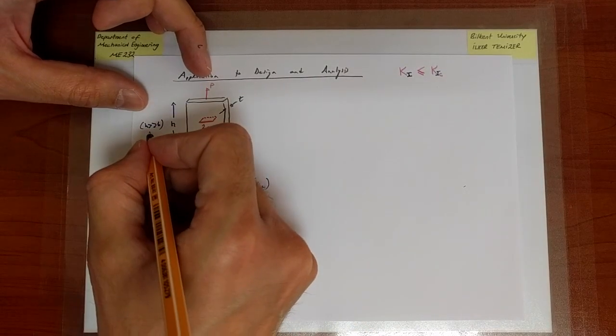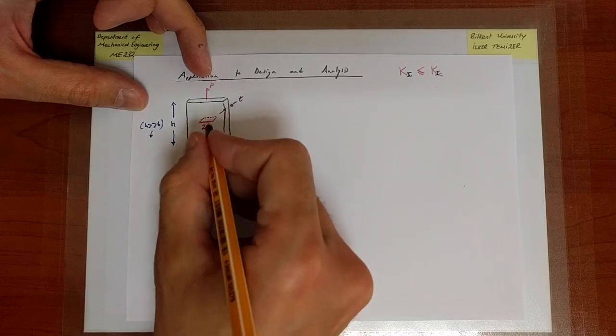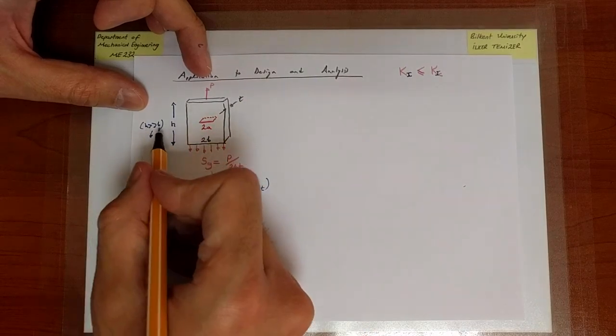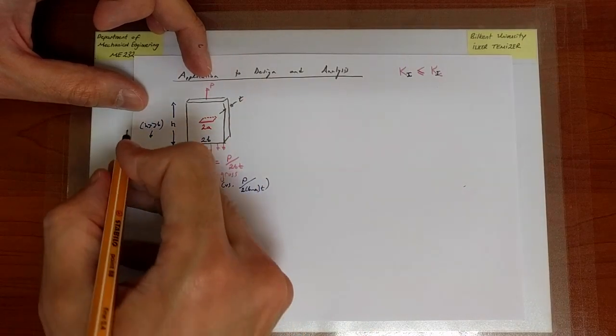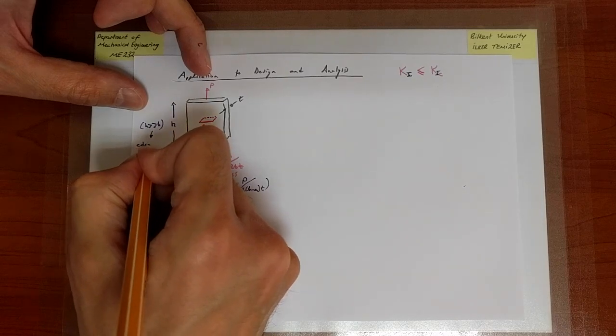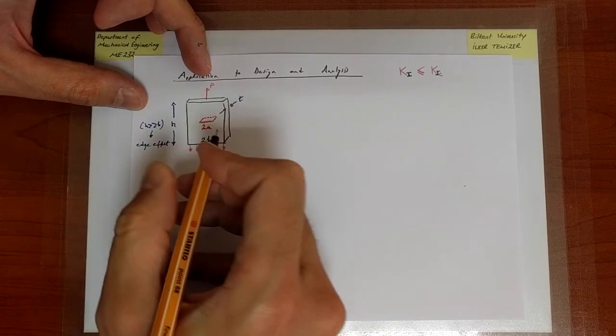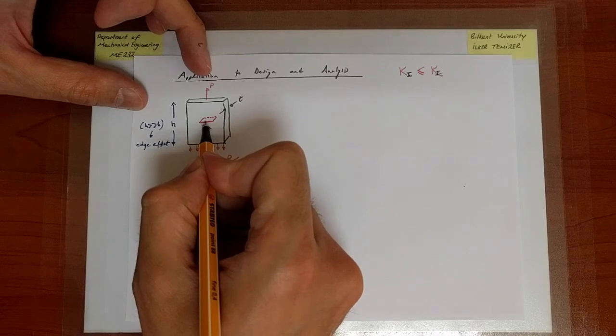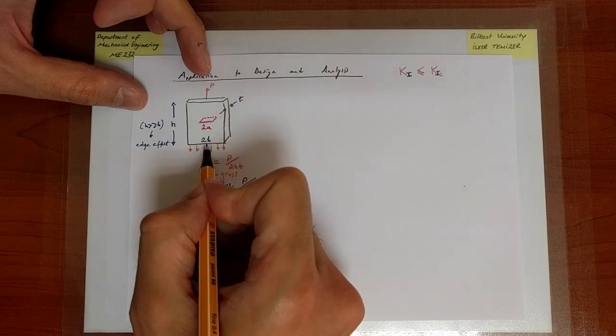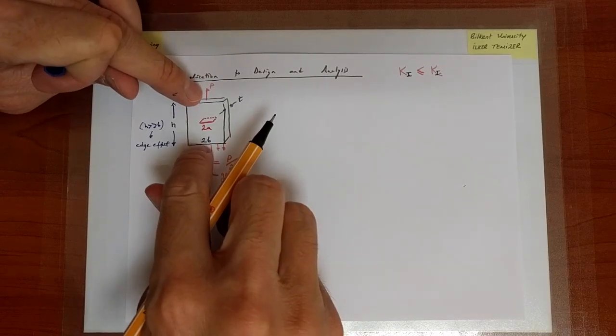Okay, so now the stress sufficiently far from the crack is uniform if this assumption is satisfied. If it's not satisfied, there will be an edge effect. In other words, you cannot move that far from the crack because the height is not that large.